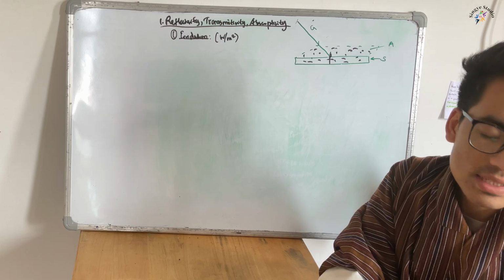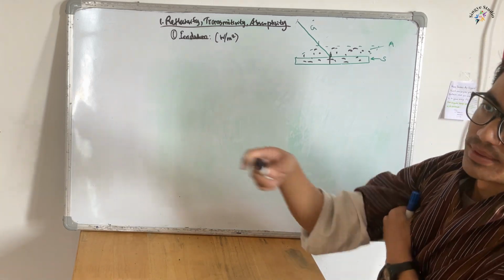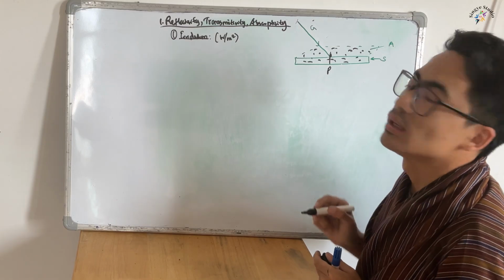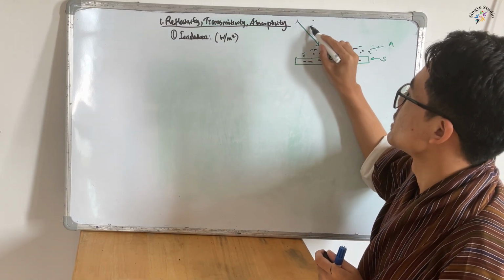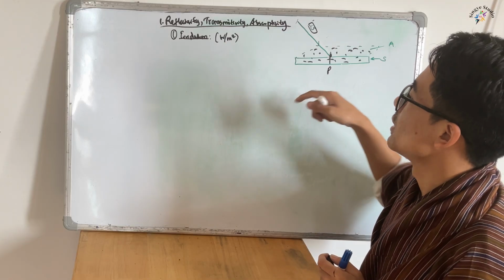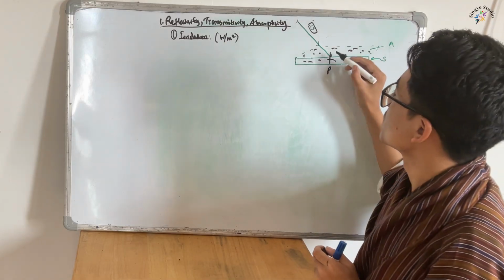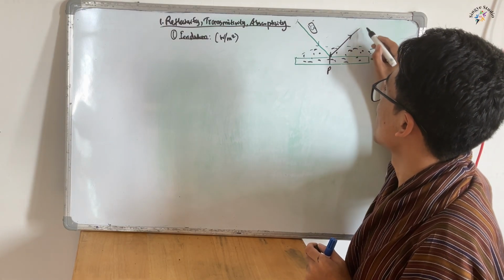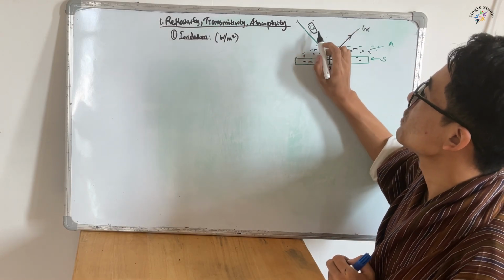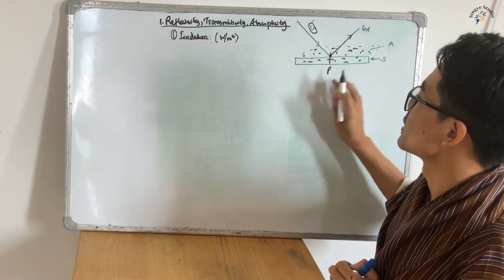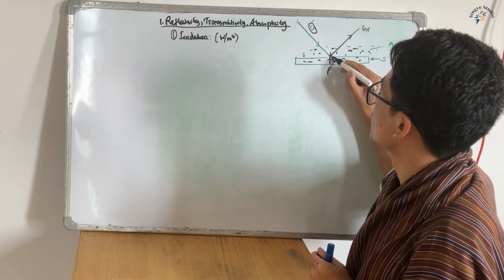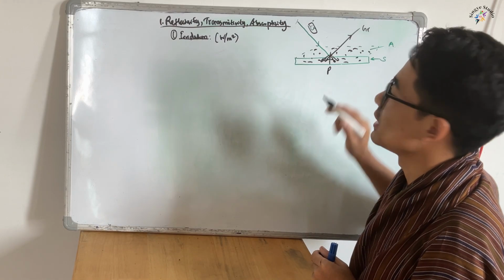I will say that there are three things that will happen. When this ray strikes at this point, which you can call P, some portion of this G, the total irradiance that you have, will be reflected, right? You can denote it like this. So GR is the portion of G which has been reflected, and then some portion will be absorbed by the solid itself.